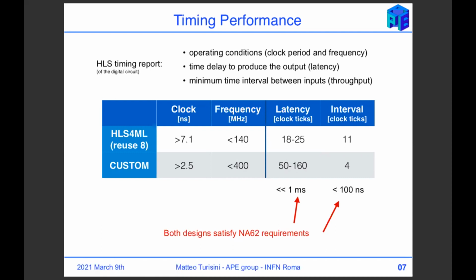And the two designs perform differently in terms of frequency and clock, but both satisfy the NA62 requirements. The third column, the latency, translated in nanoseconds, is almost at the level of 200 nanoseconds for both designs, and this is well below the NA62 requirements. And one of the things I like most is that both designs are very, very fast in accepting new inputs.